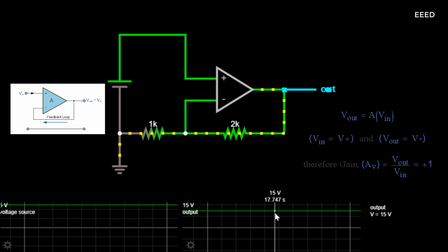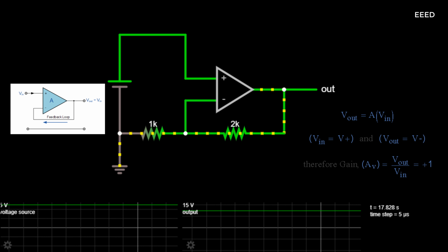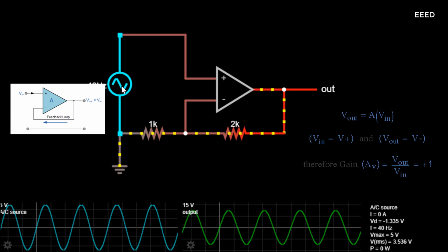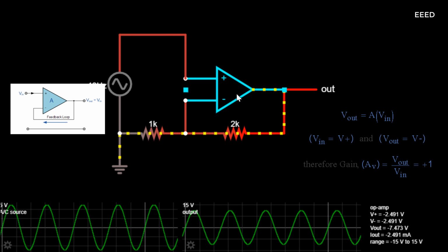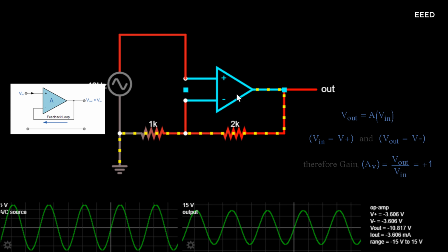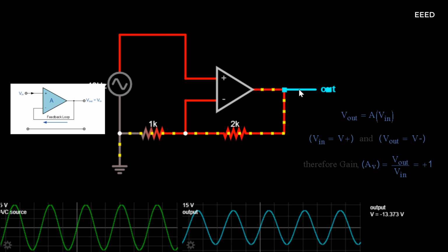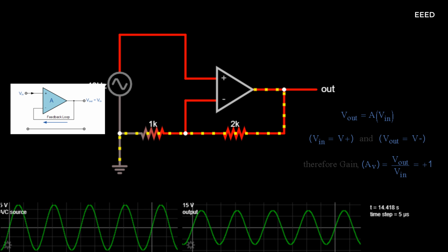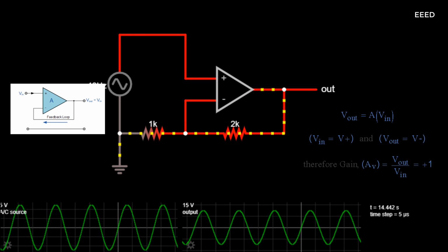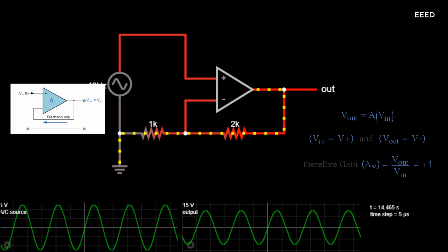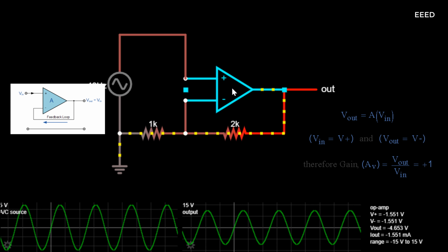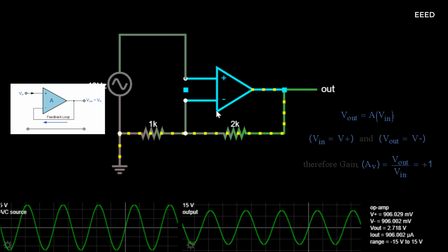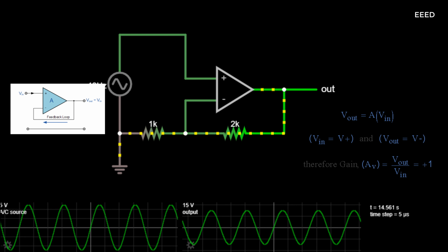Since no current flows into the non-inverting input terminal, the input impedance is infinite (ideal op-amp), and also no current flows through the feedback loop, so any value of resistance may be placed in the feedback loop without affecting the characteristics of the circuit, as no voltage is dissipated across it: 0 current flows, 0 voltage drop, 0 power loss. As the input current is 0, giving 0 input power, the voltage follower can provide a large power gain. However, in most real unity gain buffer circuits, a low value resistor, typically 1k ohms, is required to reduce any offset input leakage currents, and also if the operational amplifier is of a current feedback type.